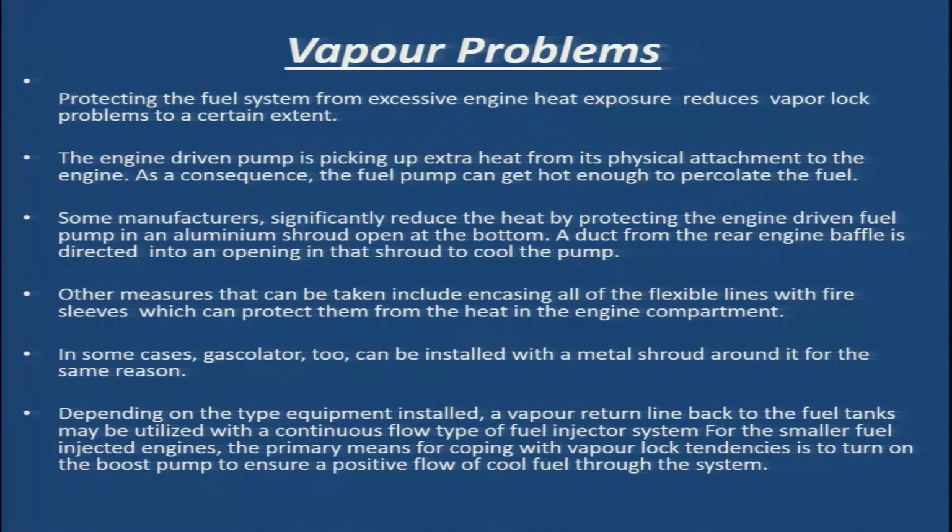Because of vapor formation, air pockets are formed in the lines, and because of these air pockets, the fuel is not reaching the cylinders and it is very difficult to start the engine during hot weather in case vapor pockets have formed in the lines.